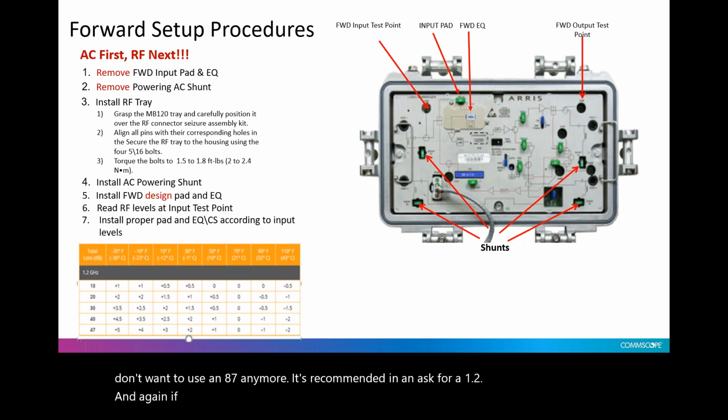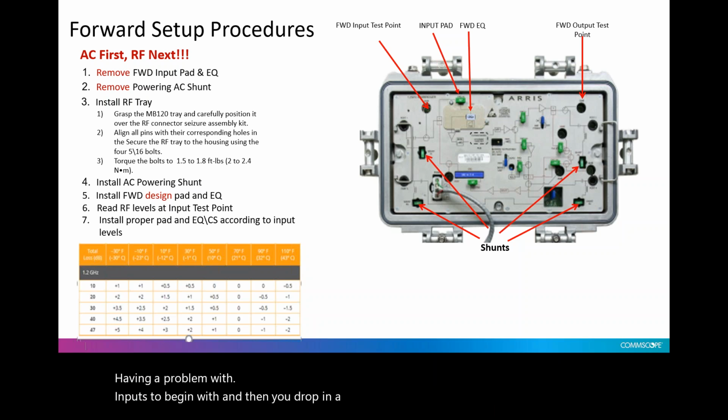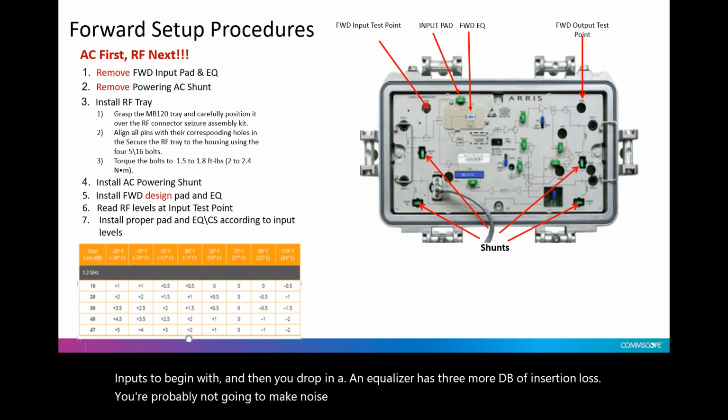And again, if you do have problems with input levels to begin with, and then you drop in an equalizer that has 3 more dB of insertion loss, you're probably not going to make noise figure. So just be very cautious.